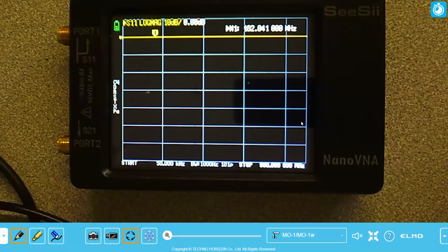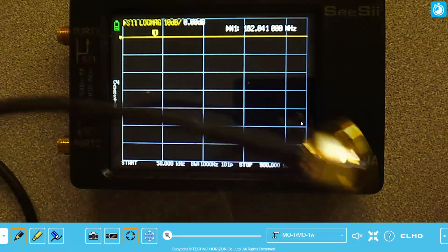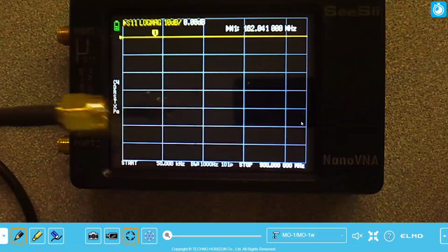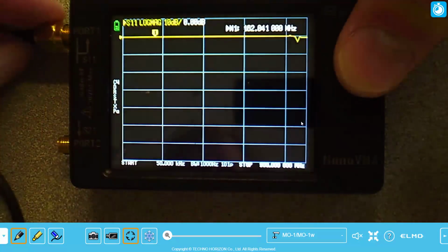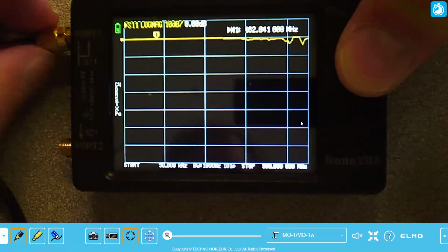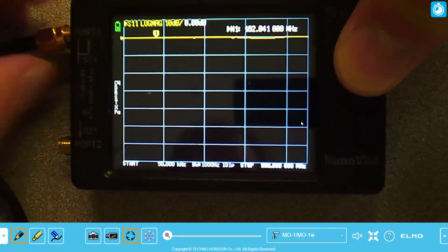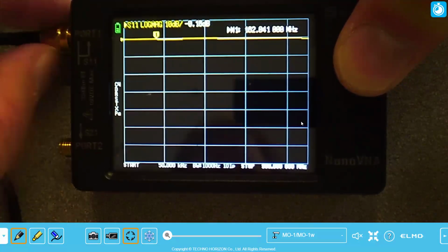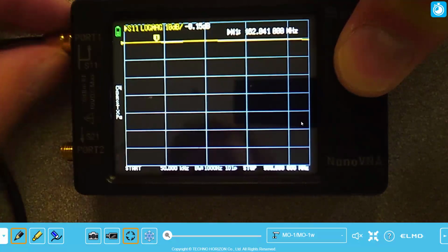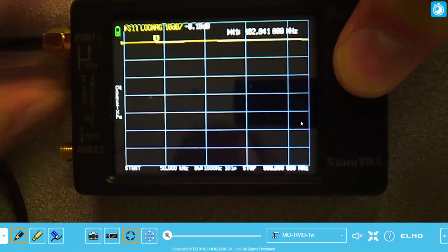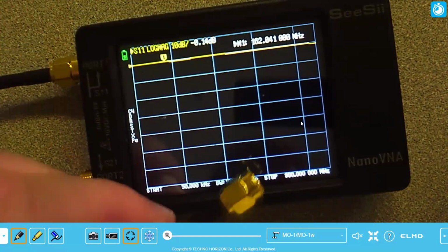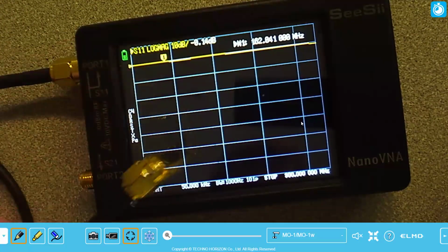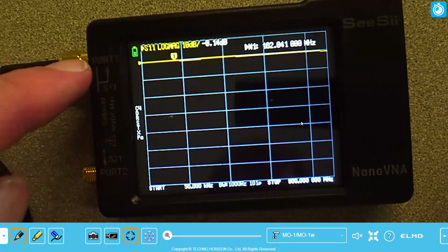In class, the very first exercise is to measure the reflection coefficient phase off of this cable. So this goes beyond the calibration. It's calibrated. I will connect this cable to port 1, and now the microwave goes out of port 1 all the way down to the end of the cable, reflects off the cable and comes back into port 1.